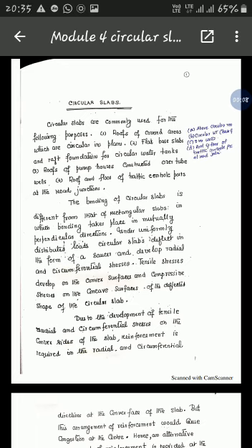You all have heard about slabs, normal conventional slabs, that is one way as well as two way slabs. So how will you differentiate one way and two way slabs? We have already seen that in the last semester. One way slabs are the slabs in which the Ly by Lx ratio is greater than or equal to 2, whereas two way slabs are the slabs where the Ly by Lx ratio is less than or equal to 2.